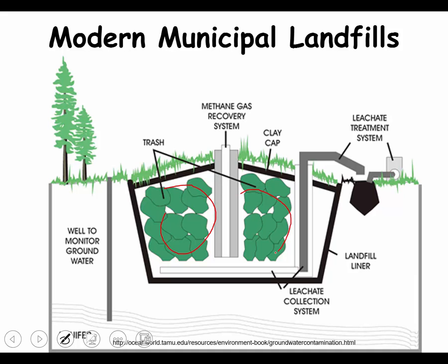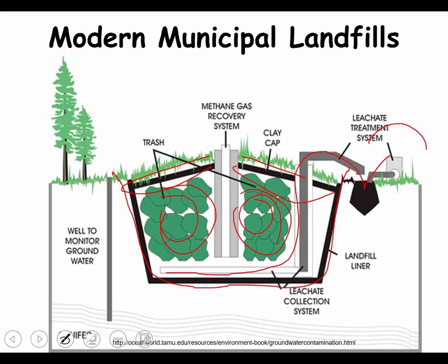Here's the trash. Here's the liner. Now, we've actually put a clay cap on top of it too, to reduce infiltration. We want to minimize the water getting in there, but there's always going to be some water, so there'll always be some leachate that results from the decay of the modern garbage, and so the liquid portion of that is collected, brought out, and treated.